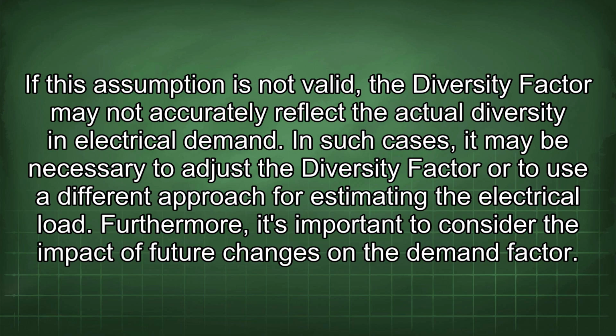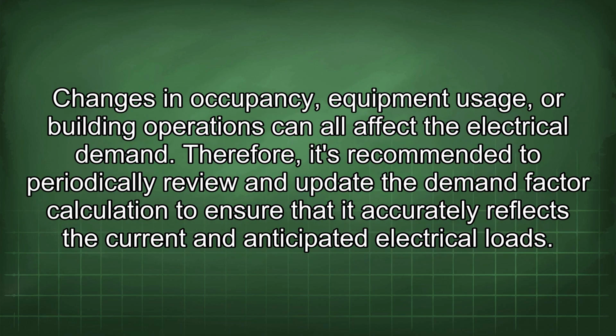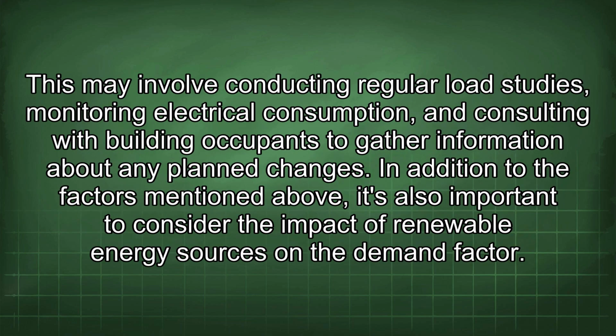the electrical load. Furthermore, it's important to consider the impact of future changes on the demand factor. Changes in occupancy, equipment usage, or building operations can all affect the electrical demand. Therefore, it's recommended to periodically review and update the demand factor calculation to ensure that it accurately reflects the current and anticipated electrical loads. This may involve conducting regular load studies, monitoring electrical consumption, and consulting with building occupants to gather information about any planned changes.